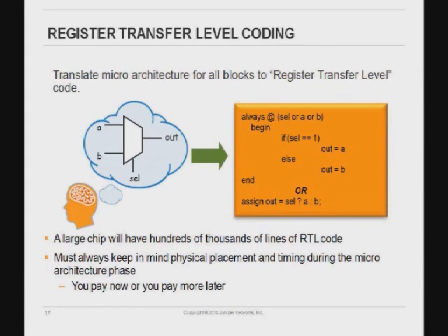And the other thing is that although they look like C, they are not software. They will get translated into hardware. They will have devices corresponding to them. So that's something we need to keep in mind when we write these C-like RTL codes. If you don't, things get spread out and take a lot of gates, the performance will go down, and you will have to modify your design.